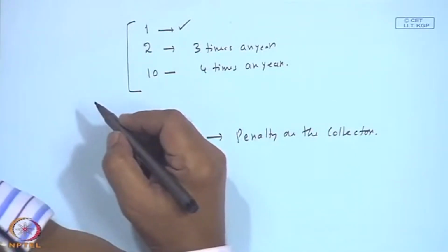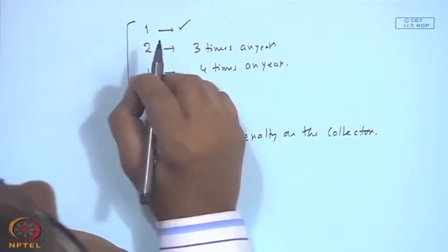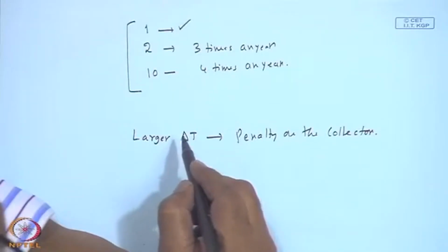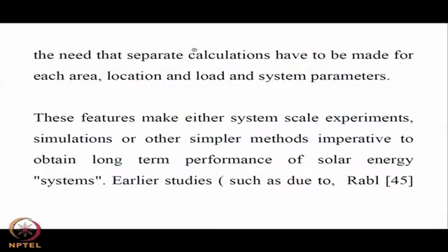You are asking the solar collector to deliver energy at a much higher temperature if the load heat exchanger is poor, and hence the collector will be operating at a lower efficiency, and hence you have a higher curve or a lower load fraction met by the particular system.